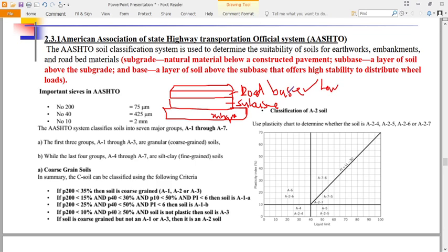Why should it be of low plasticity? As we shall discover in chapter 4, the strength of the material is influenced by the water which is held by that material. If you have a material which has high water, the effective stress, or the load-carrying stress, of the material is equal to the total stress minus the pore water pressure.